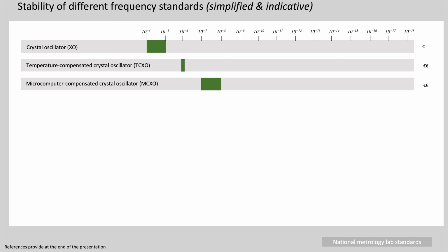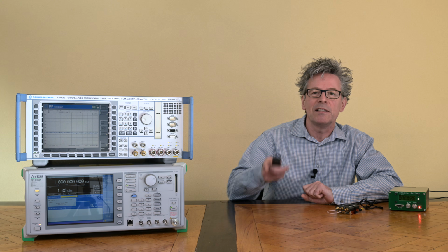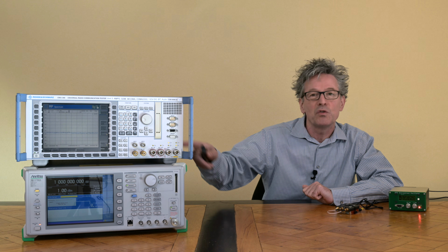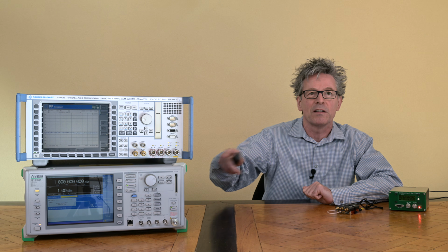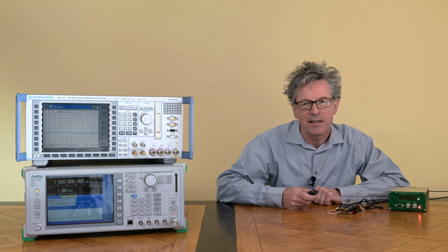And what is quite common if you need a very precise clock is that you take a crystal and put it in an oven at a constant temperature. I think it's like 60 or 80 degrees Celsius, and at that constant temperature the crystal behaves in a more accurate, more predictable way. That is actually the type of crystal that is right now in these two devices. Both of them are equipped with oven-controlled oscillators. We are at 10 to the minus 8.